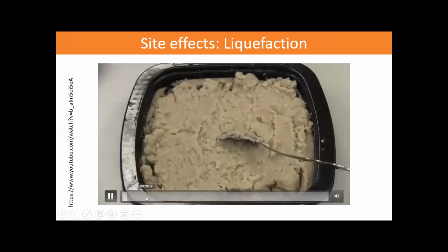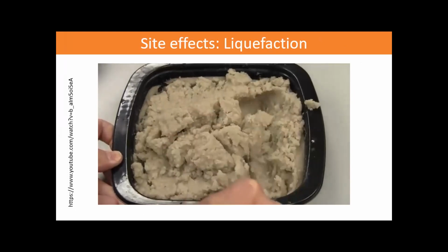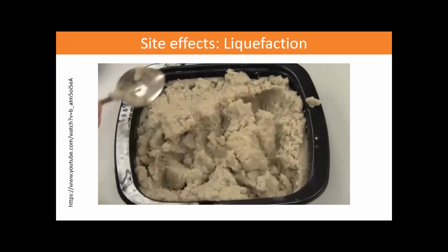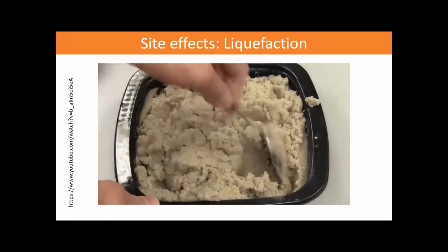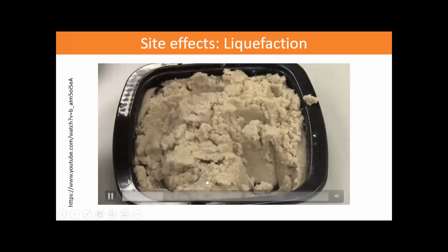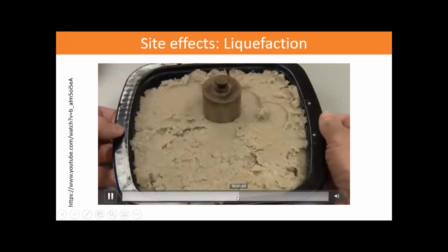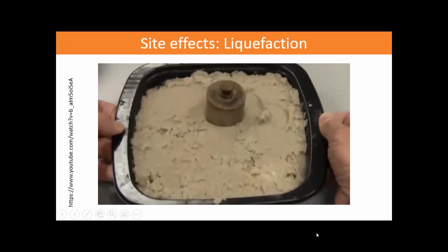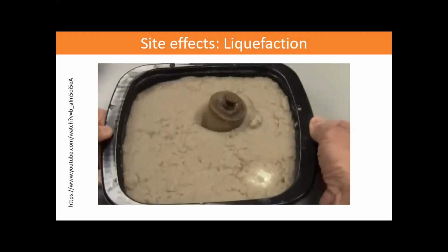So this is an example of liquefaction. This is just regular old play sand that you can put in your sandbox at home. Once it's wet and you add water to it, they're going to end up tamping this down and putting some type of weight on it. So as he's just shaking it, that weight is going to sink into the sand.